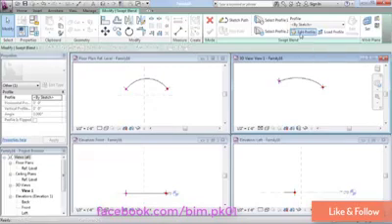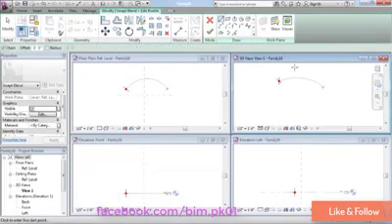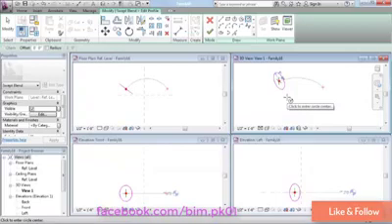So I'm going to choose Edit Profile for the first sketch. I'm going to keep these sketches fairly simple, which means I should be able to work relatively successfully here in the 3D view. But what you start to see if you look at each of the views is if my sketch was more complicated and required a little bit more precision, it would become rather difficult to work on it in any of the views that I have available to me. Down here, I'm skewed to the angle of the plane. Here, I'm skewed to the angle of the plane. The plan, obviously, is not a choice at all. 3D is okay, but it's not fantastic.